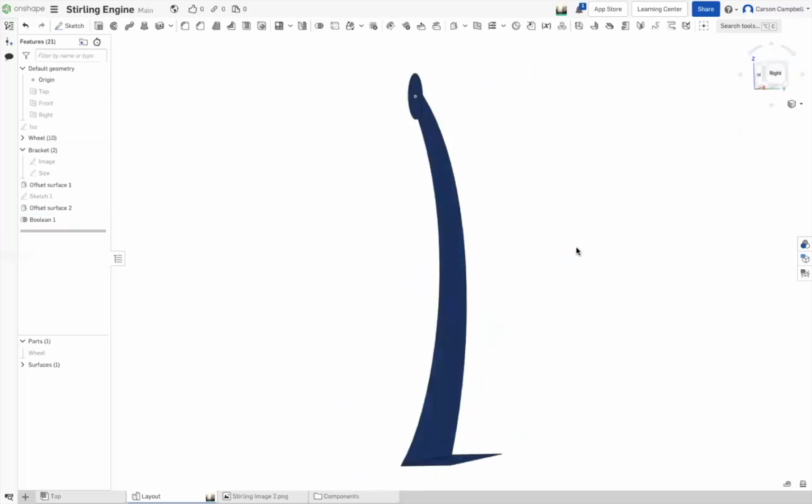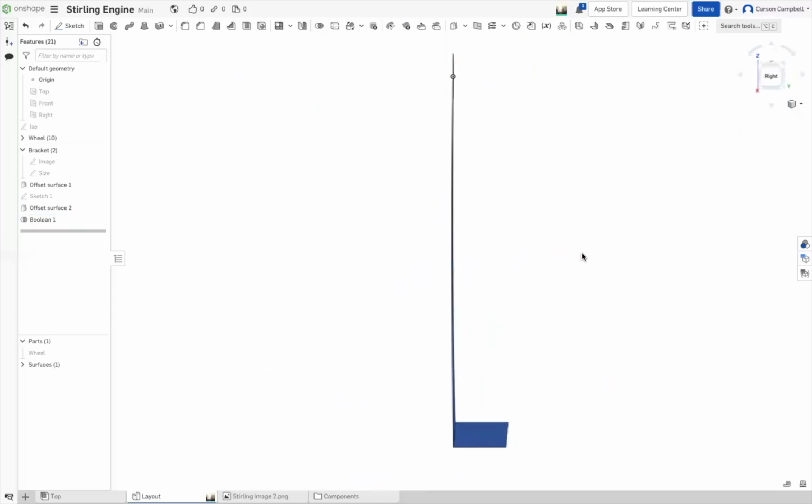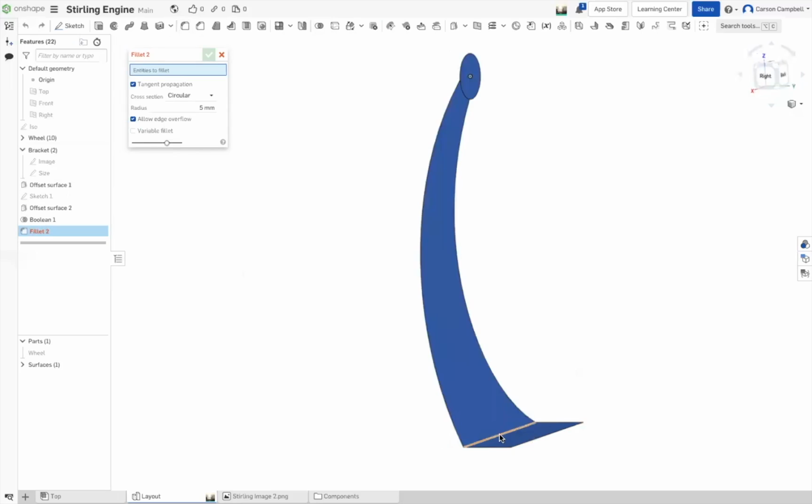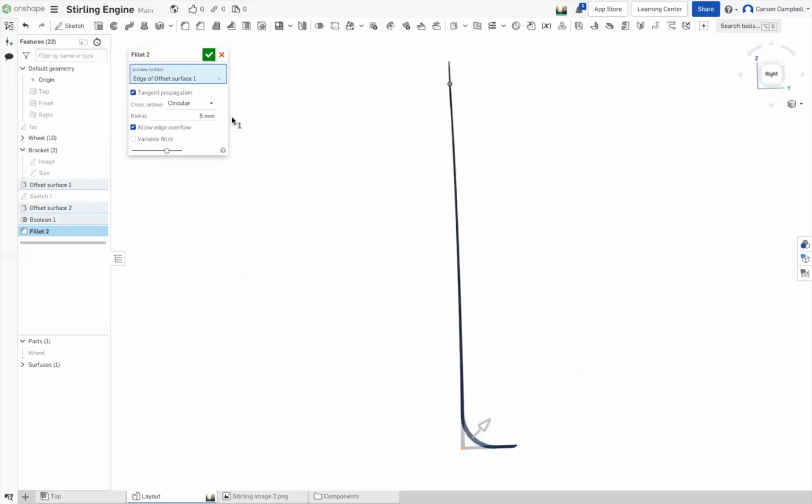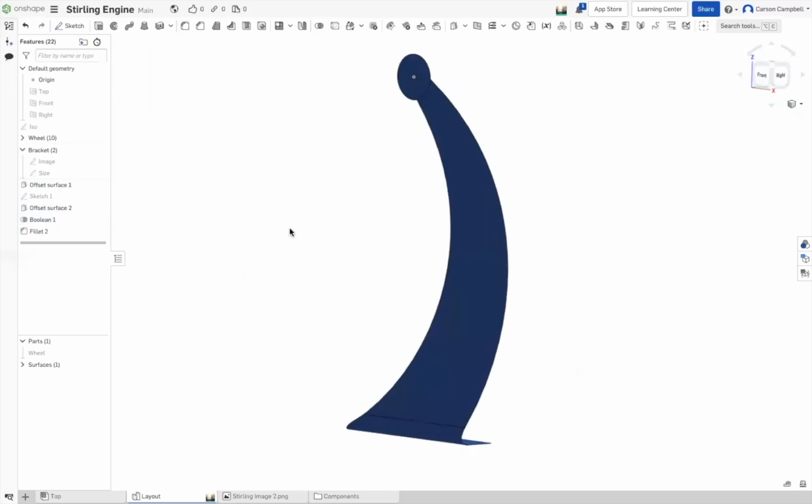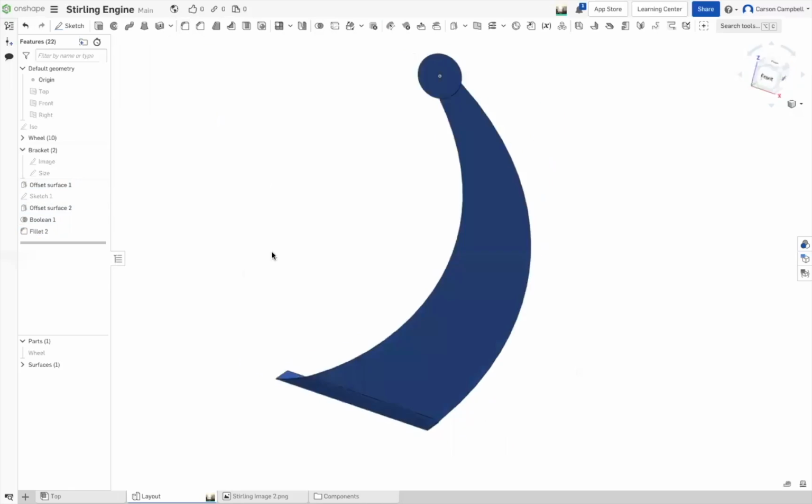Now let's go in and we can, there's a couple of ways to do this. One thing is, let's go do a fillet, put the fillet down in the bottom corner. Here? Yeah. Do I want this whole line? Yeah. And you want to change that to about a 3 millimeter radius. And then you can say okay, and we'll spin it around. All right, and then up here, let's thicken this.